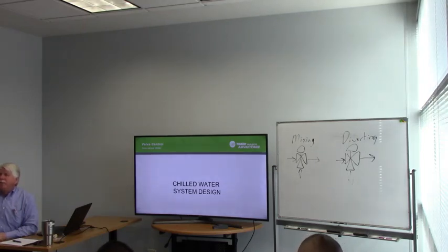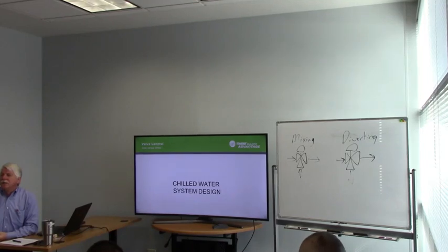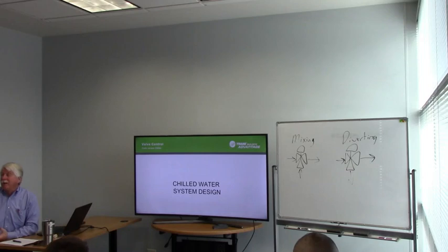Right, but it would help these guys to identify when you're talking about supply and return, kind of identify it that way. I mean, check the pipe, make sure it is really true, because you can have a fitter out there that can put it in the wrong spot. Absolutely. And the main place you really need to be careful about these is in large hydronic systems when you have a reset valve, but it's a butterfly valve, or it's two big valves that are linked together on a T. And that becomes very important how they pipe it.